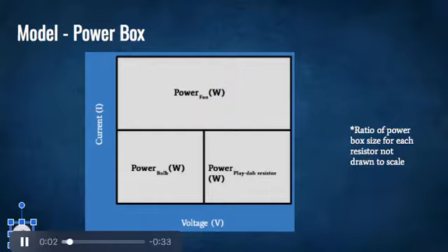The following is a powerbox representation of our circuit diagram. It displays how current and voltage are split between different elements of the circuit. To explain, since the bulb and the Playdoh resistor were placed in series with each other, the voltage is split between these elements, but since these elements were placed in parallel with the fan, current is split between those elements.